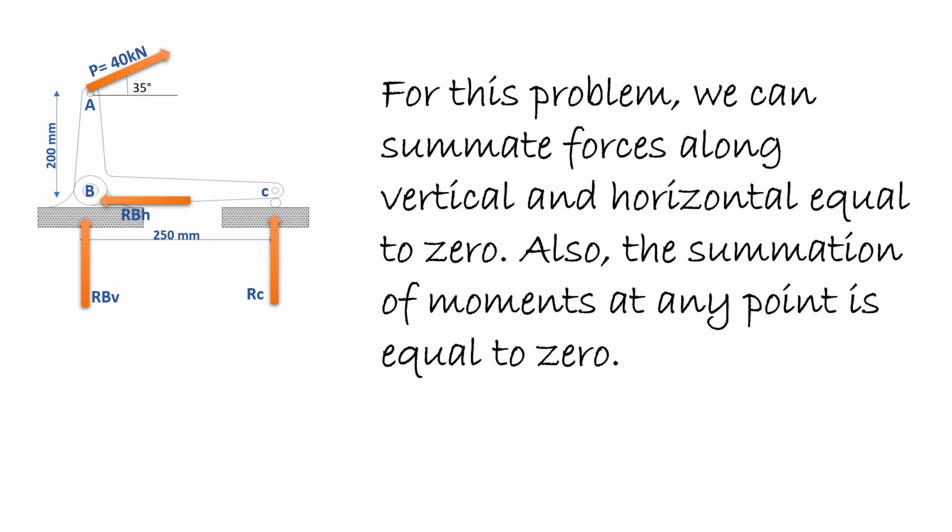For this problem, we can sum forces along vertical and horizontal equal to 0. Also, the summation of moments at any point is equal to 0. Why 0? Because we want this system to be in static equilibrium and we don't want it to move. And we want to calculate the stress of the pin that will keep the system in static equilibrium.